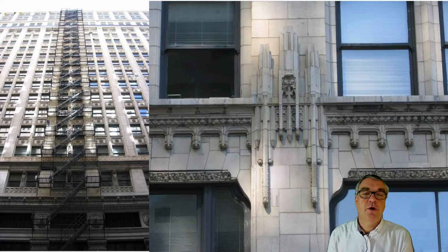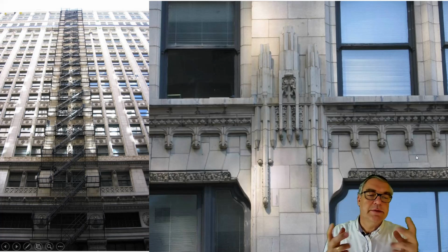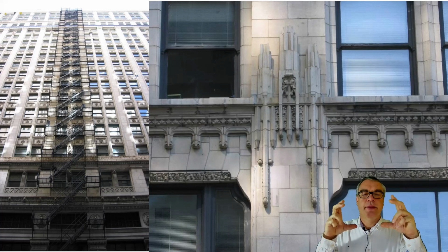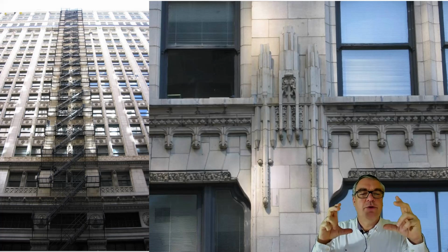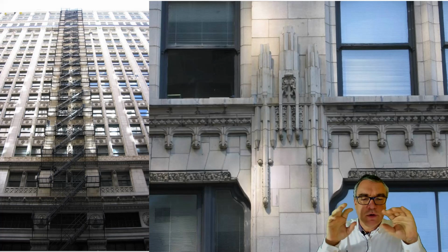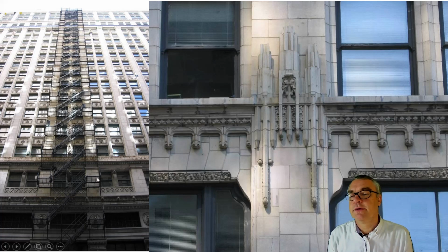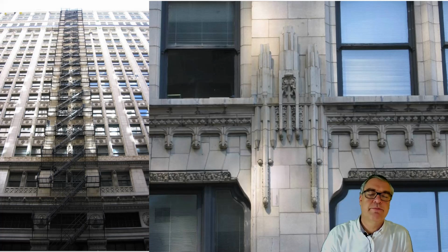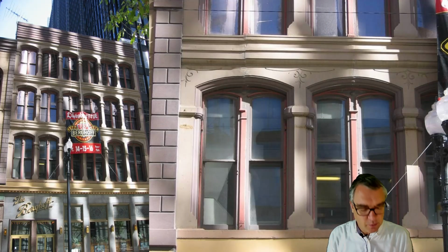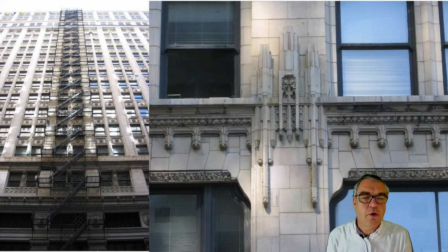The same here. It follows a certain aesthetic. It even follows this aesthetic when we look at these arch-like systems. But as we now know, there's a steel structure behind, and all these natural stone components which look like being dead load oriented are fixed to this substructure, so they're not taking the dead loads of the main system, which we identify by the similar size of windows through all the floors, a dimension which expresses that the dead loads are not taken by the outer layer, but by an inner structure as a system. Interestingly, this could be done in natural stone or artificial stone or bricks.